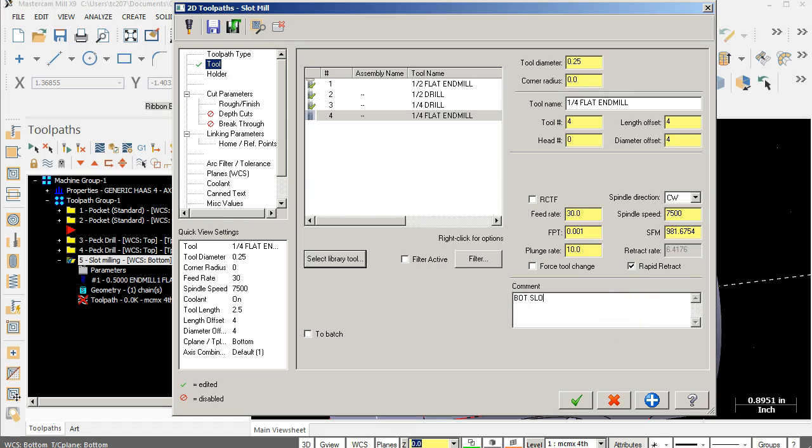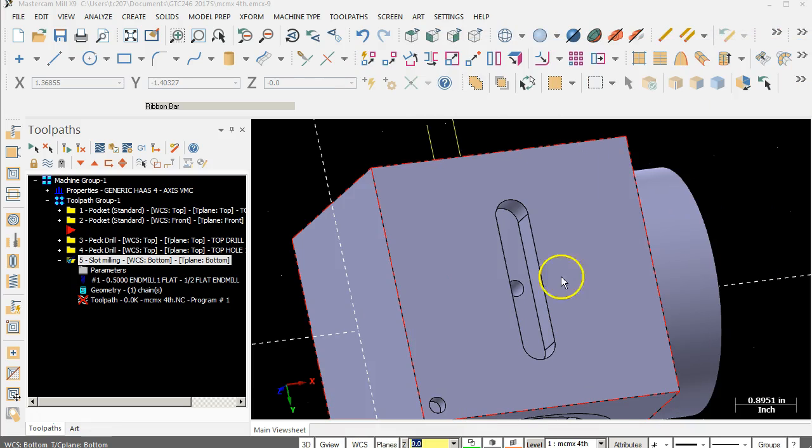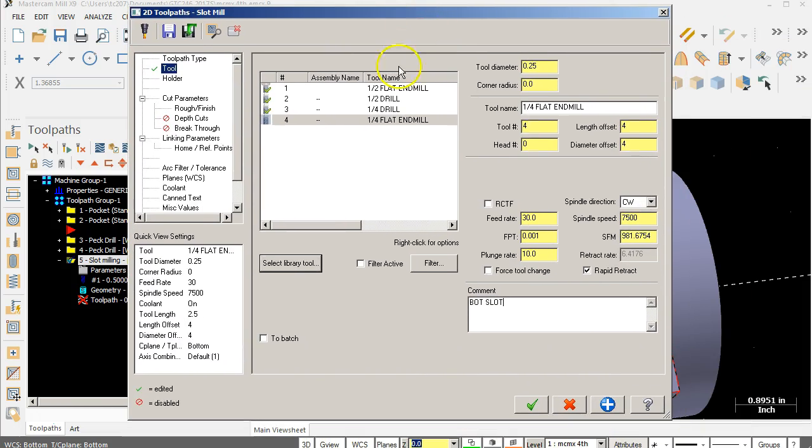Why not like a 3/8 or something like that? Well, depending on what you have, but is there? If I need something smaller elsewhere, I'm probably going to need something smaller elsewhere. If I know for sure, then yeah. Plan on using the 1/4 inch somewhere else. So. Yeah. It may come back to that these holes are drawn as flat bottoms. I put a drill point in there and it goes to inspection and comes back, no, those have to be flat bottoms. I've got a 1/4 inch tool lined up for it. My story, and I'm sticking to it.